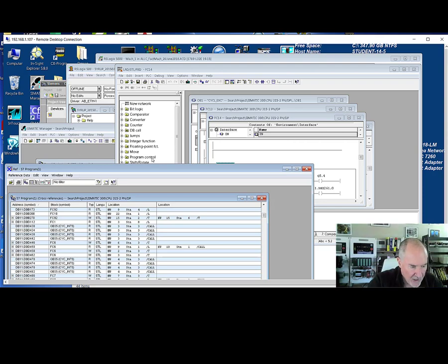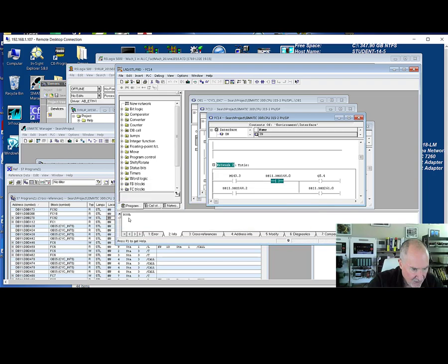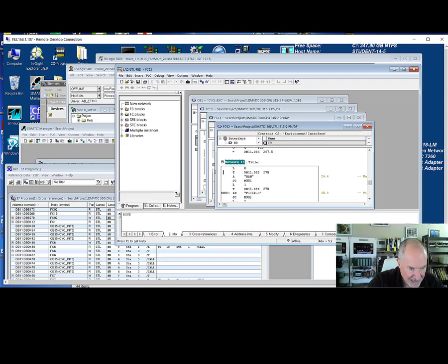So I think what we're going to do is we'll look at DB11. We'll go ahead and show you that if I go to this, it will go to the location at which it changed. What this did is it took 0 and it transferred it to db11.datablock_byte270, and it wiped it out. So it wrote a 0 to it and changed that entire byte all at once. And the rest of these DBBs would do the same thing. So that's a more difficult example.